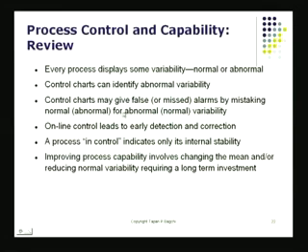It's possible that control charts would give you false signals. It's very possible that the variation that you see is normal. But remember alpha error. Alpha error is the type 1 error committed with a control chart, which says I get a signal. That means I see a point beyond the upper and lower control limits on a control chart. And I go witch hunting. I try to sort of diagnose the process.